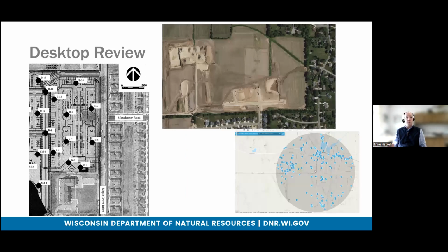First step, as Jeree mentioned earlier in the design process, is a desktop review. We can do a very similar task for constructability. We can look at our previous, as a contractor, previous site experience. If we had installed utilities or other features on that site in the past, we should have some understanding of what those soils are like.